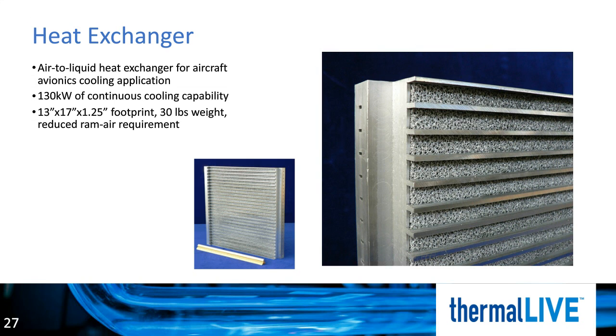Larger pore size uncompressed foam was used on the air side to minimize ram drag, while small pore compressed foam was incorporated into the thin liquid channels. In airborne applications, size and weight are both at a premium, and this 130 kilowatt unit measured only 13 by 17 by 1¼ inches and weighed roughly 30 pounds.